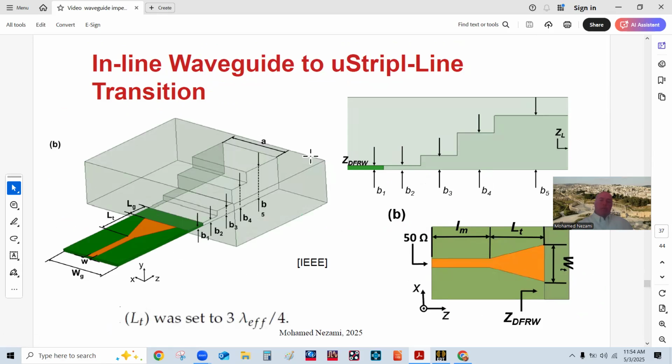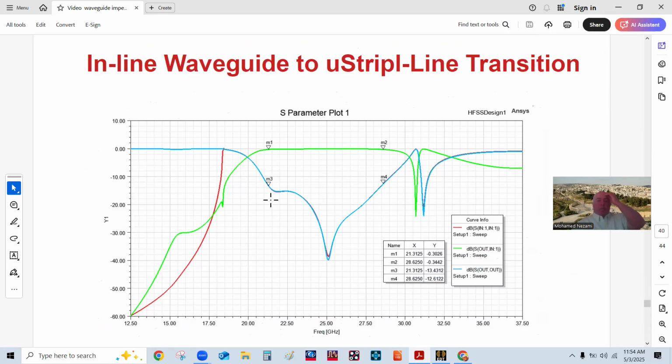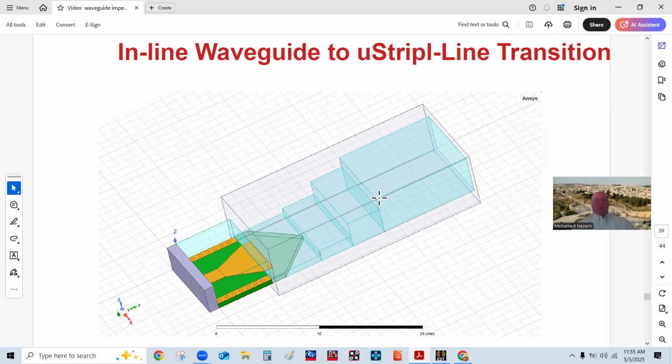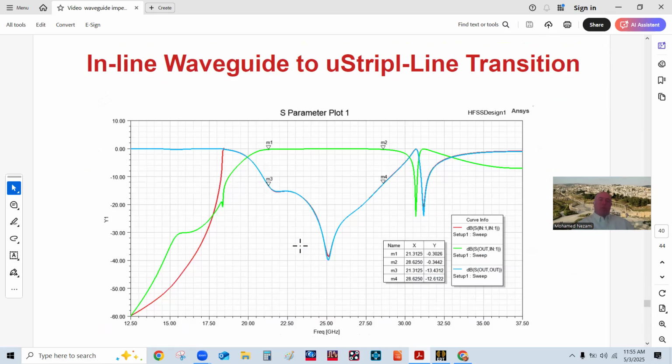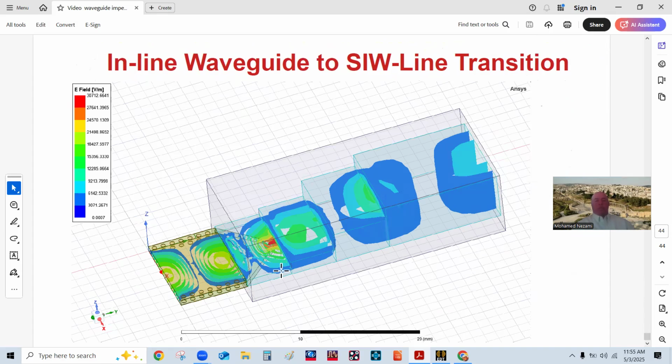Okay. So another view of this, of course, the length of this transformer in here, this is really a transformer also between the dielectric filled waveguide and the 50 ohm microstrip line. We use 3/4 of a wavelength to do this here. Okay, while these ones in here are really a quarter wavelength inside the waveguide. Okay, so basically we're going to redesign these two, except this time we're going to use more details than the first video.